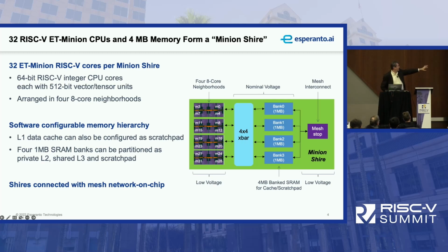So this chip was designed to run at a nominal voltage of about 400 millivolts, when the normal voltage you'd see off NVIDIA or somebody else would be about twice that on a chip, okay? The dense memories, though, you have to run at a nominal voltage. That's because the fab makes those cells so tiny they can't tolerate changes in voltages. So part of our expertise is knowing how to divide up the different voltage domains and frequency domains on the chip, in order to balance all of these out to give good performance on your applications here.